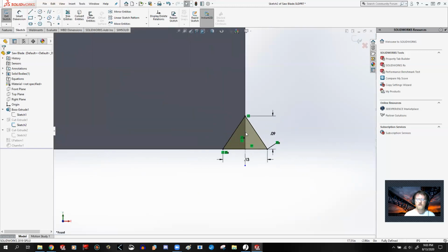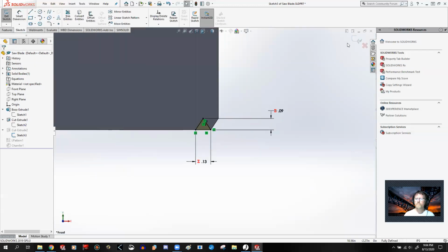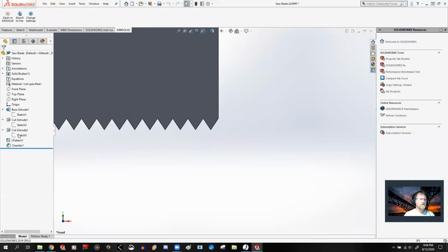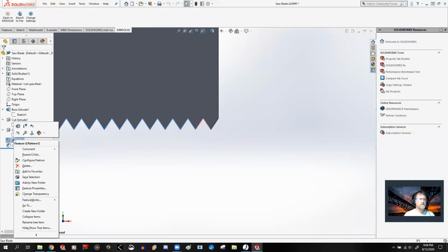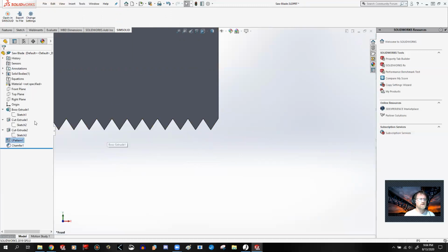not this, although this is a little triangle here. It's the next bit where they might not make this triangle equal to the other one. And then when they do this linear pattern, they sometimes refer to the wrong one. Sometimes they refer to, instead of the second one, the first one. So that when that pattern goes for 130, they actually end up with 129 teeth, not 130 teeth. So make sure that you've got two of those triangles. One refers to the other, then the linear pattern refers to the first one.